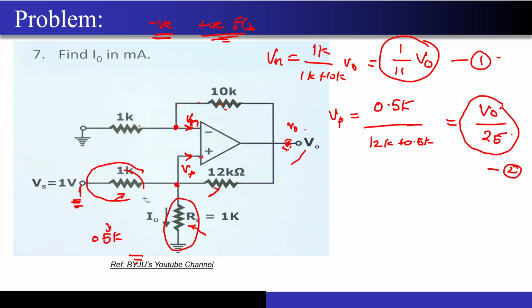Excuse me. Yeah. Is there a rule of thumb as to how much stronger the negative factor has to be than the positive factor to apply virtual ground? Okay, so see, we just want to check which feedback is actually dominating. Even if the negative feedback is slightly stronger than the positive feedback, that is still okay. The problem actually arises when the negative and the positive feedback exactly become equal with respect to each other. So even if it is very slightly larger than the positive feedback, you can still apply the virtual ground. All right, got it. Thank you.